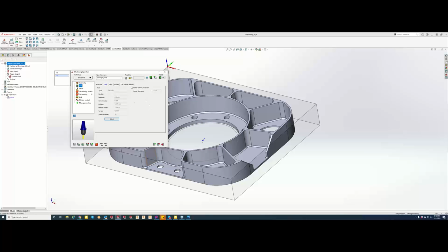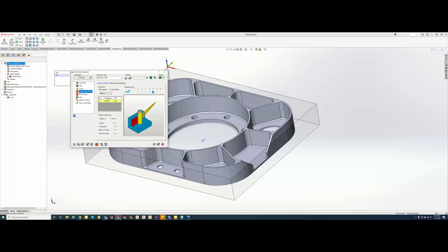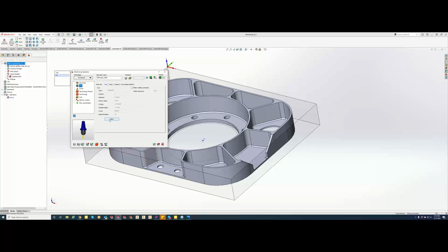And by doing that, we can go right to our technology wizard right here, and we can see that this area is in yellow right now. That's telling us that that tool will cut it without any issues, but it is not the ideal tool. The ideal tool will be green, but you guys will see 3 different colors in here: red, yellow, and green. And if you do get red, that's not saying you can't use that tool at all. It's just that you won't get the optimal performance or the longevity using that tool. So what we can do is a little testing.